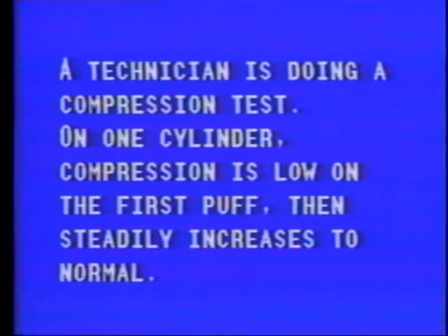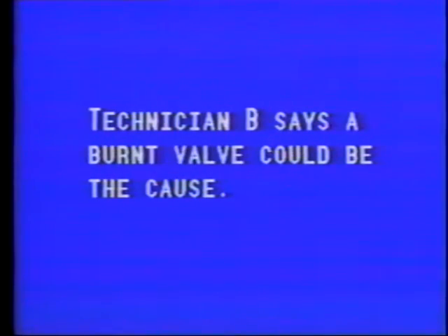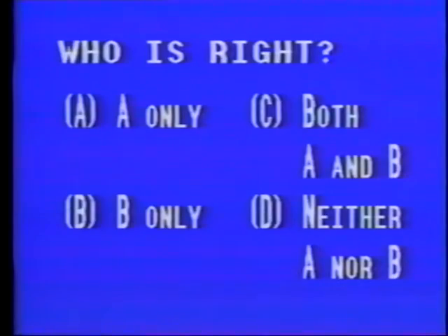A technician is doing a compression test. On one cylinder, compression is low on the first puff, then steadily increases to normal. Technician A says worn piston rings could be the cause. Technician B says a burnt valve could be the cause. Who's right? A only, B only, C, both A and B, D, neither A nor B.